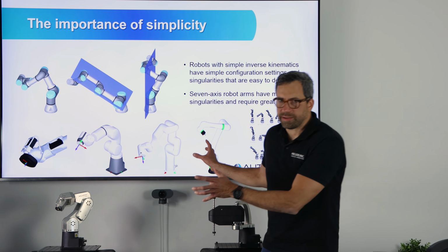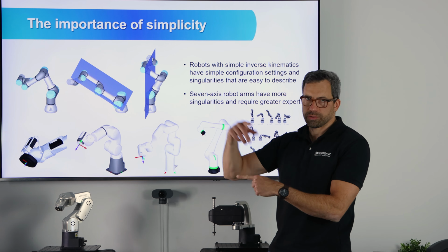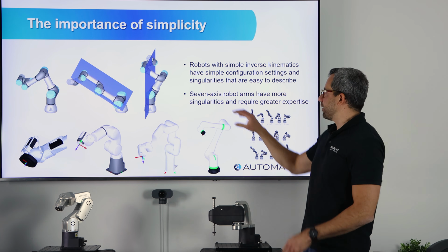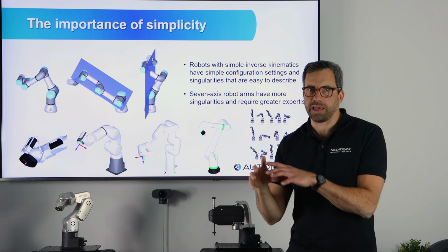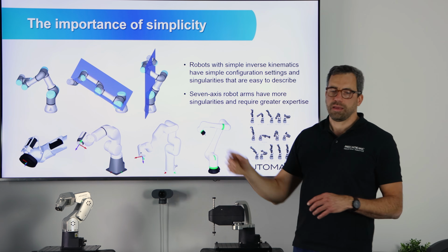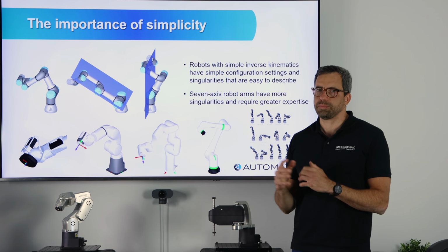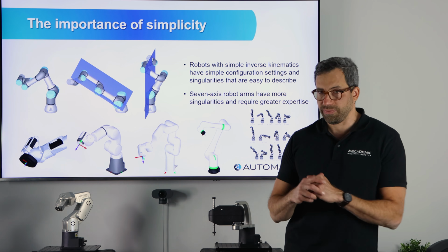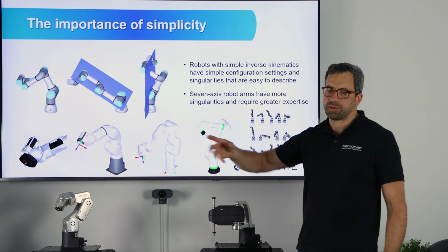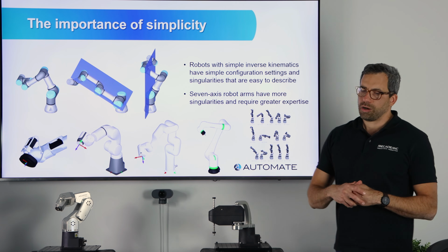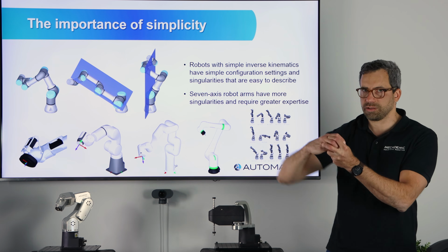So there is the robot architecture of a 6-axis robot, the way the 6 axes are arranged, one with respect to the other. But then there are also the 7-axis robots. Previously they used to be reserved for the Canadarm, for space applications, for research applications. Now there are a lot of companies making 7-axis robots, and many of these are really great. There are definitely advantages of using a 7-axis robot. You can avoid obstacles, and I also thought you could avoid singularities by using this redundant degree of freedom.